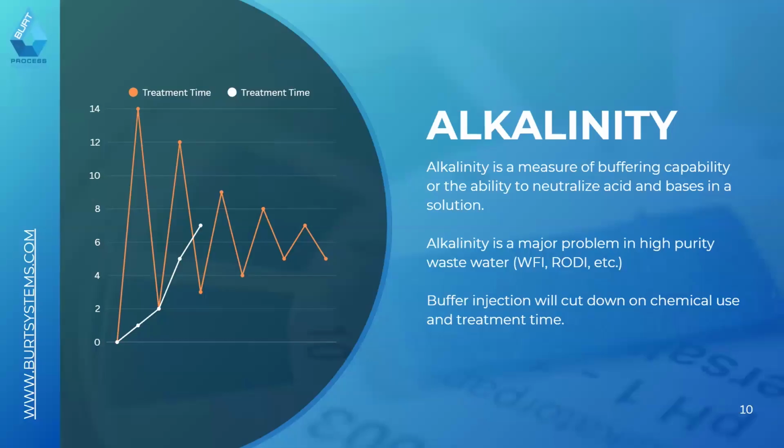very problematic. The thing with citric acid is it's a weak acid. So even at a very strong concentration, it has a pH of like 3, whereas say your sulfuric acid has a pH of like 0. So you're talking 10 million times stronger effectively. So what can end up happening is if you have a very large waste stream, now you're putting in a substantial volume of this chemical, even though it's safe, to basically allow you to treat pH.